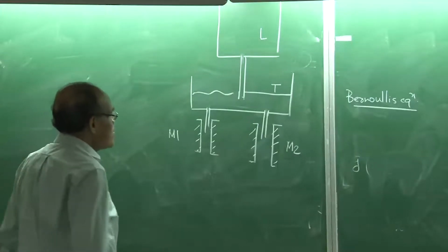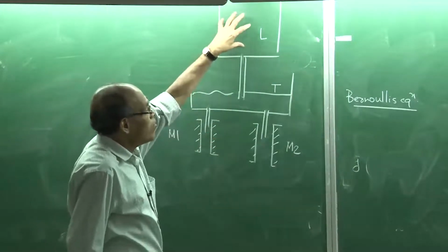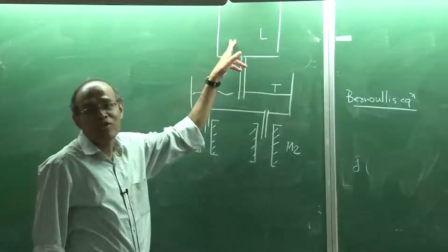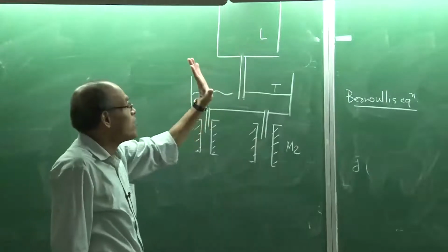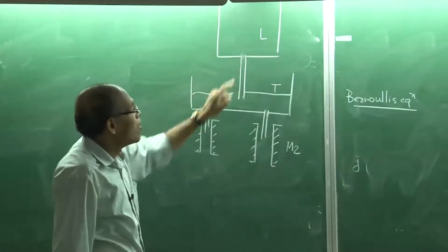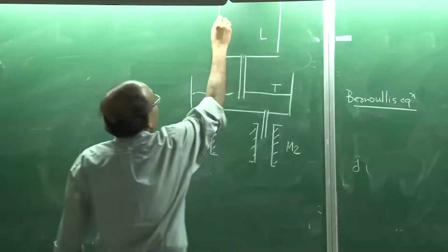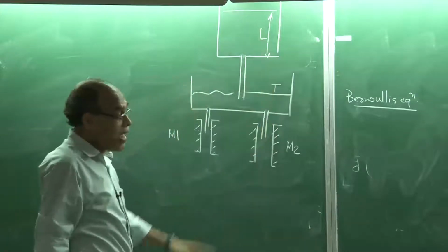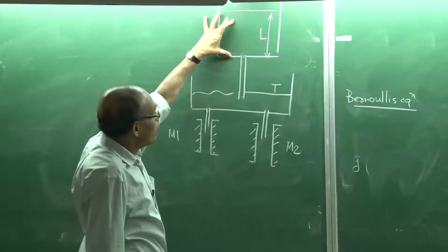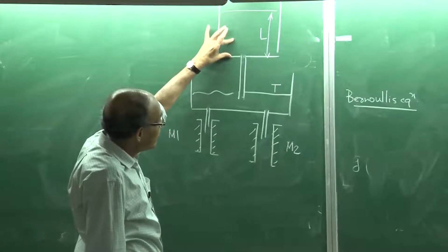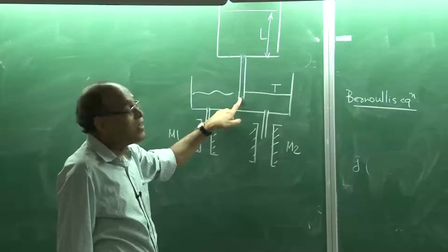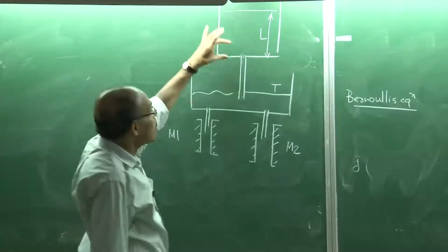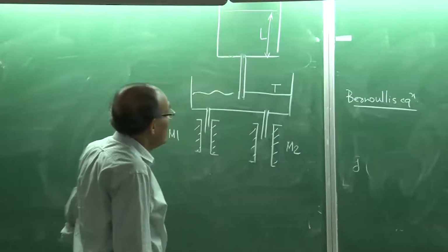Basically, what happens is, you can expect that because these flows are all gravity driven flows, there is no pump, nothing like that, okay? No external work is being done. So, the moment I open this hole or the aperture, molten metal starts to flow in. These are driven by the liquid head. You can imagine, and we will show that, when the head decreases, the velocity is also going to decrease. For higher head, the velocity or the flow rate is going to be larger, and for smaller heads, the velocity or the flow rate is going to be smaller.